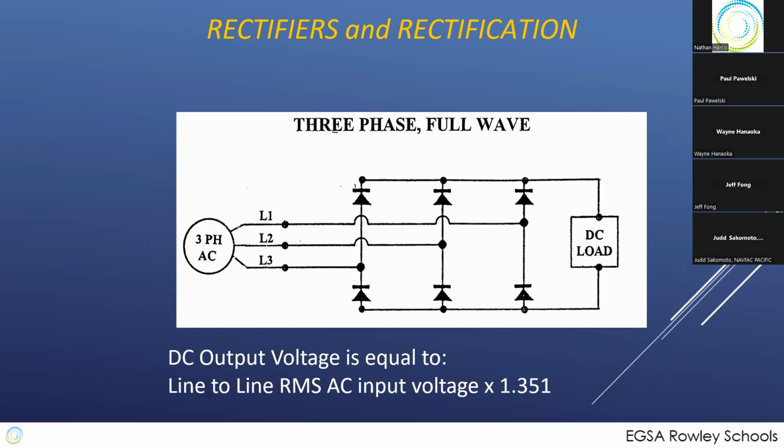This is what's preferred. This is a three-phase full wave rectifier. It's got 6 diodes on it. Kind of makes sense why that disc we saw earlier had 6 diodes on it, which we talked about, and how the generator is making DC voltage for its internal circuits. Now, the interesting thing on this is you can do it off a delta connection. You don't need a Y and a neutral, because when this is the highest voltage, the voltage on the other 2 lines is less, which means there's always a return path for the load to come through.